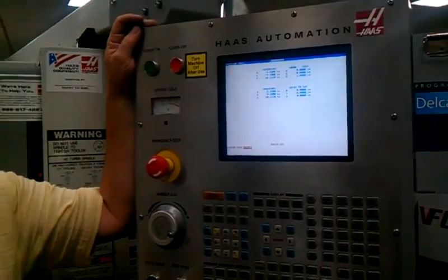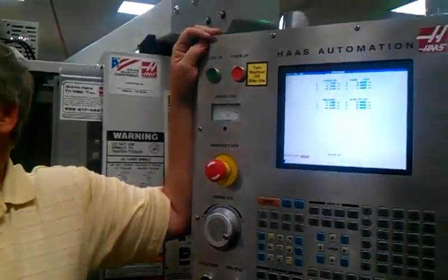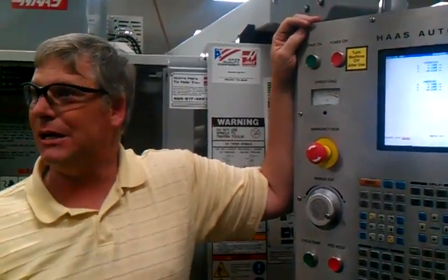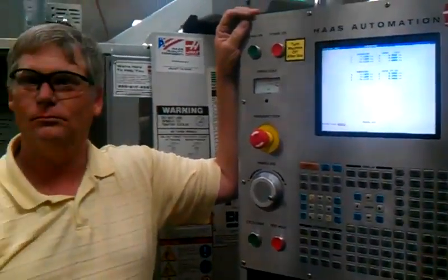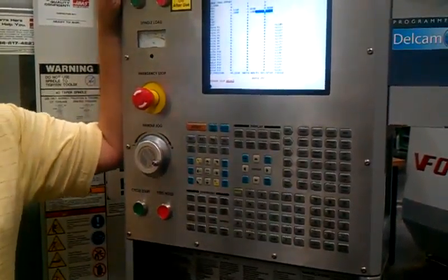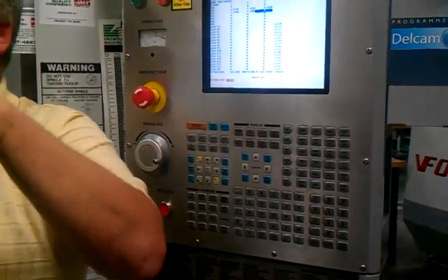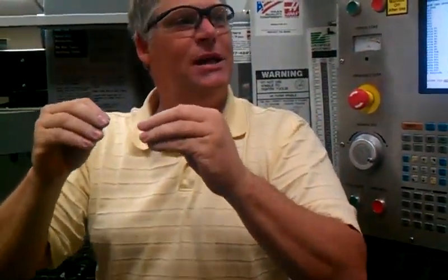So you don't have to put Z0 on your G55 because you already put it in your height offset? Right. I don't have to have an offset in my 55 for Z because I'm controlling it with my tool length offsets. And that way I can use my G55 Z. I can adjust all of my tools up and down, can't I? See, if I put a minus 10 thousandths in G55 Z, all of my tools are going to go 10 thousandths farther down because I just shifted them 10 thousandths in the Z minus direction.